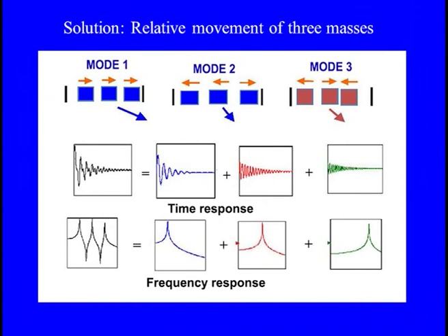If we want to see the relative displacement of the masses for the 3 degree of freedom system, you can see that mode 1 shows all 3 masses along one line in the plane, in phase. So, these are in-phase vibrations. In mode 2, the 2 adjacent, closer masses are in the same phase, and the other mass is going towards the other side. And in mode 3, the adjacent masses are in repulsive action, whether we take M1 and M2 or M2 and M3.